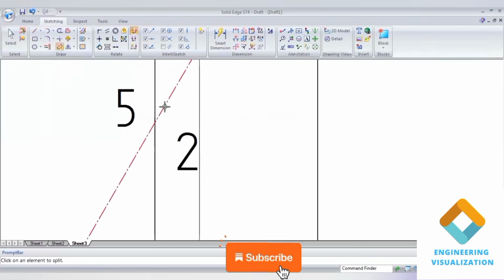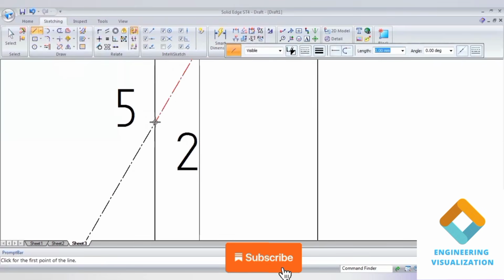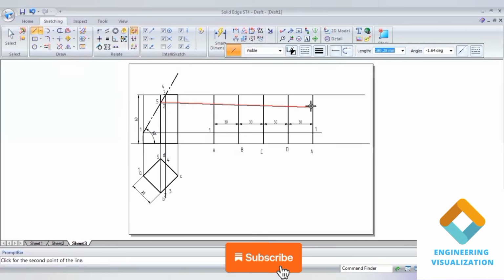So I can use the split command here, so that I can get the exact point. I'll go to the split command and split it exactly where the section plane is cutting. Okay, so now I'm getting the exact point. From here I'm going to project it.